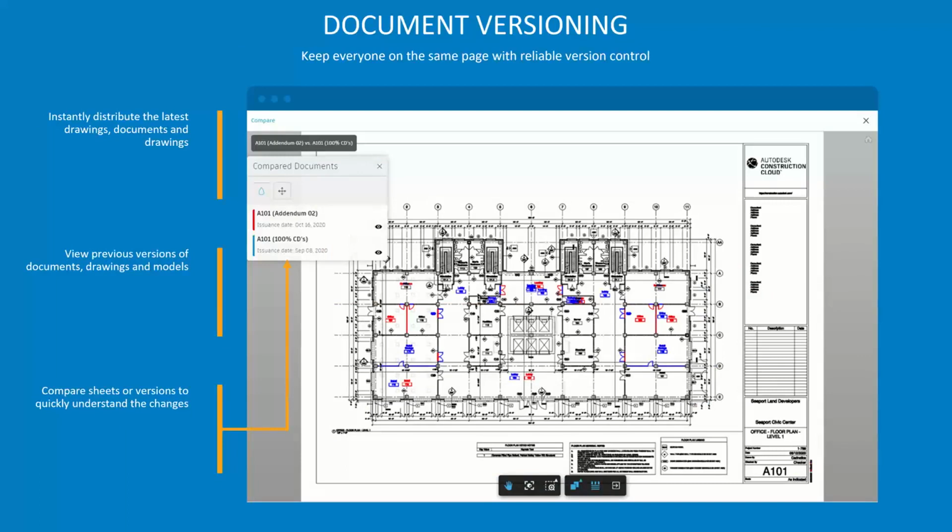As I mentioned before, we also have the ability to version our documents. One great thing that we can do is either through PDF or through publishing. If we do have BIM Collaborate Pro and we're publishing views up to the cloud, we can check versions between different documents. This screenshot is just a pretty basic one between two different package releases, or whatever you would want to call that, published releases, where we're highlighting elements that have changed between one version release of a document to another, and we can isolate those objects.